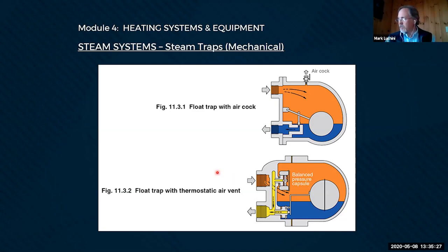Remember, when a steam system is cold, when it's not on, there's no call for heat. The boiler's not running. It's empty, right? It's actually not empty. It's full of air. So I've got my nice cold steam system. Somebody turns the thermostat up, and the boiler fires up, and I start making steam, and I start sending steam down the pipes.